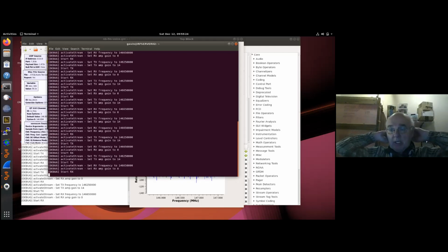I understand what you're saying, and it's a great idea. I would caution you, though, remember what I said earlier. You have to make sure that your impedances at the input and output of each switchable amp are controlled at 50 ohms. And you've got to be careful how you turn on and bias your power amps so that they're not transmitting or powering up before the antenna switch gets to the desired position. But yeah, I understand exactly what you're saying. It sounds like a neat system.